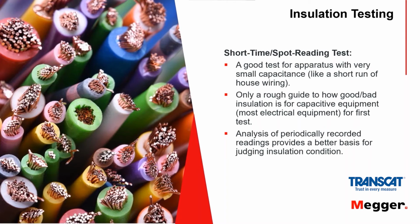If you're trying to meet a standard, let's say telecom, for instance, they install a circuit, they want to see 100. Typically, I think it's industry standard. They want to see 100 megohms or more. If they don't get that out of a newly installed circuit, they're not happy. So, okay, you do the test and you pass 100 megohms, you're done. You can move on. Or similarly, looking for a problem. You spot where the problem is, or you see that a piece of equipment is not the problem because it's well up in the megohm range, and you stop and you can move on.